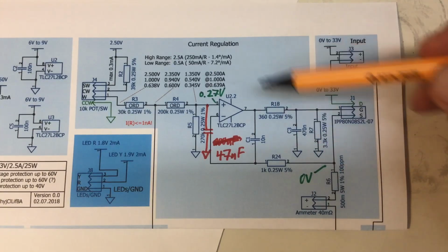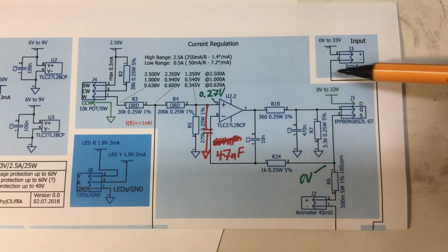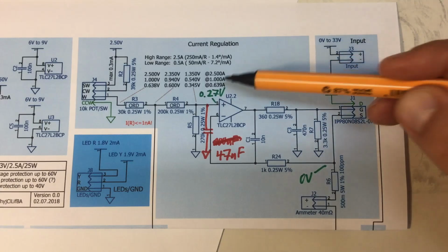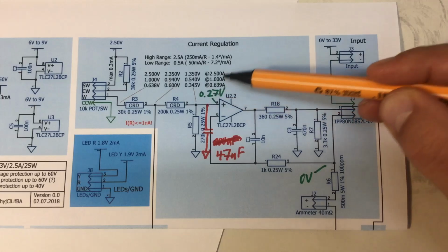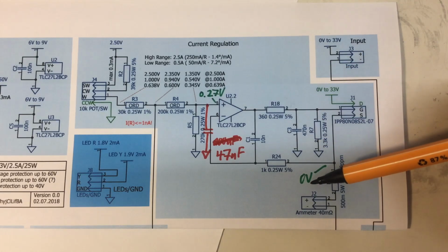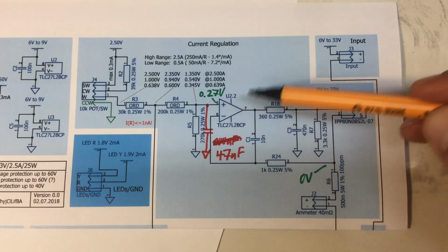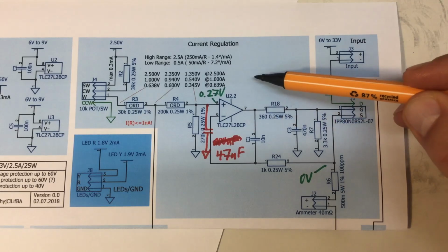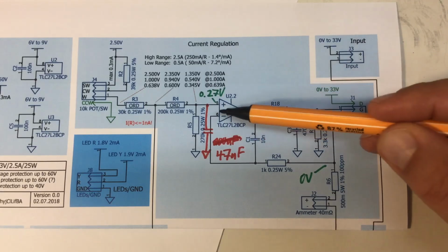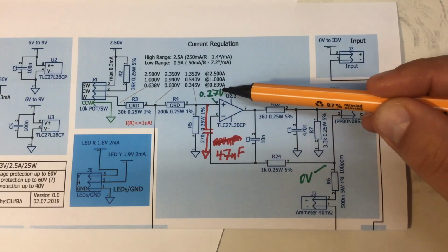And you see the problem. As long as no load is connected here, and we have our set voltage for a specific current, the op amp drives its output high, because it wants its negative input to be as high as its positive input.